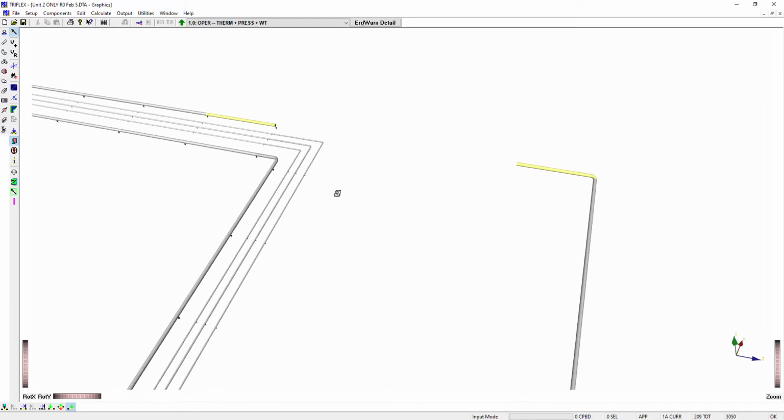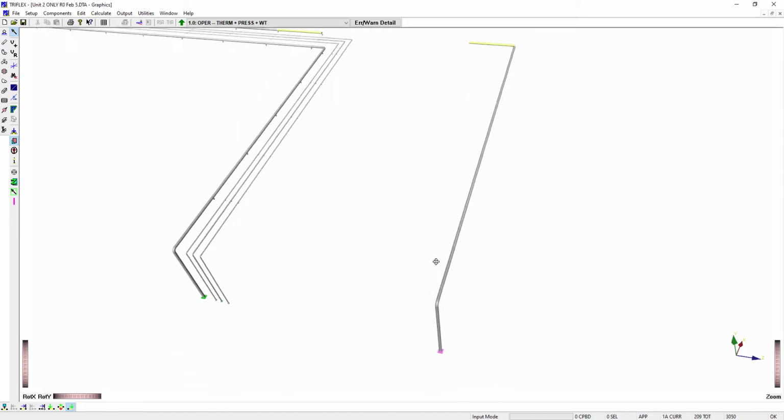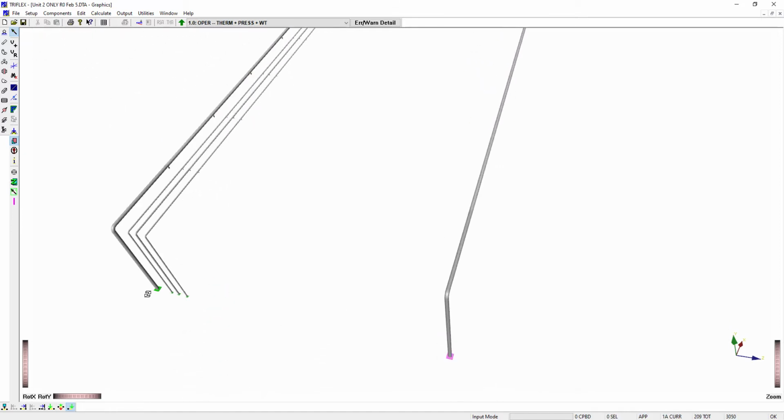Now, what I needed to do was cut about 30 feet out of these sections here. I've already done the other ones. In TRIFLEX, you can tell it to reconnect, so you wouldn't really have any need to do what I'm showing right here. It would actually reconnect for you as long as your anchors were free. Okay, as far as a coordinate axis.